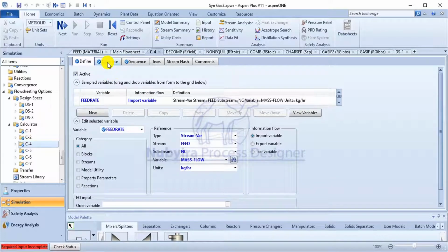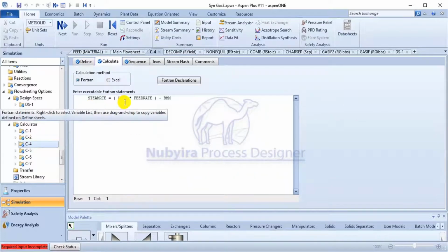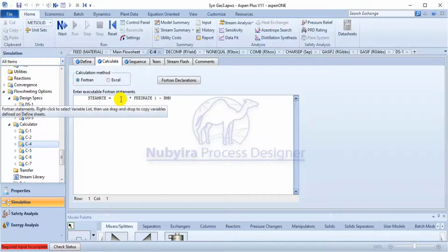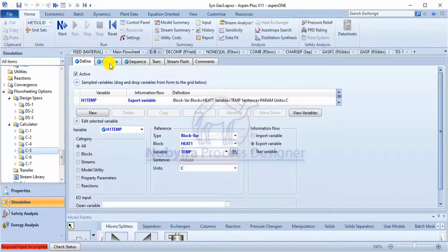We have the steam rate, so we have the steam to biomass ratio. This is the formula for the steam to biomass ratio, the quantity that was 0.73. You multiply it with the steam rate, then you add the total water that is sent to the process, just total water, since biomass contains some water too. So this is the steam to biomass ratio, 0.7. We are going to be varying these two. So we have the calculator.